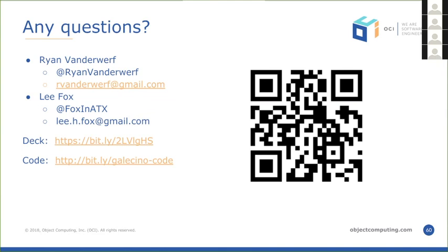As far as training, the model would have to be enhanced to include object detection layers, and then you'd have to obviously train it by setting up some scenarios of it avoiding things. You may need a little motorized fake cat or something to go across the track to make it learn to detect these things. There's an API available that you can use in the cloud. The problem is the computation power is not awesome on a Pi, obviously. People are using CUDA cores, like that NVIDIA car, for example, which has a whole trunk full of CUDA cores to be able to process stuff like that in real time. It takes a lot of power to do that.